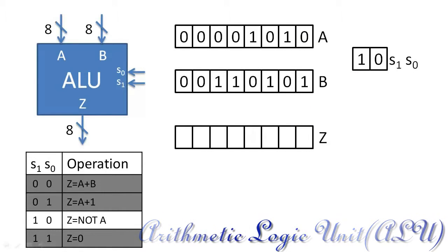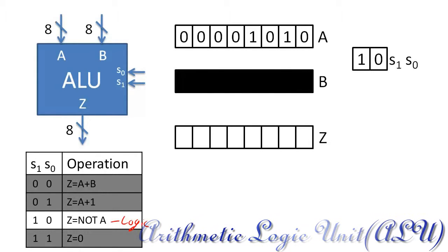To briefly introduce the logic operations, we will examine one of the simpler operations, such as the NOT operation. The NOT operation receives only one set of inputs, so again, the ALU will ignore the inputs from B. The NOT operation changes all zeros to ones and all ones to zeros. The NOT operation is applied to each bit in the register individually, otherwise called a bitwise operation.